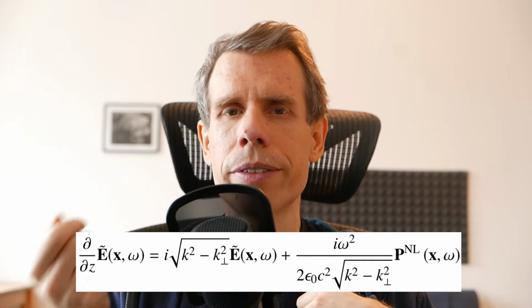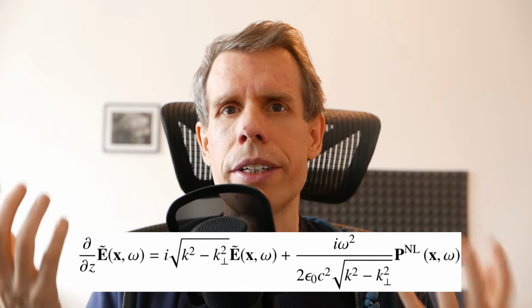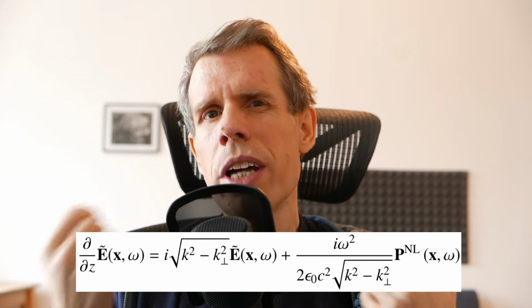So first, let's talk about what's going on under the hood. In numerical photonics, most of the time we're solving some partial differential equation. Inside of Lightwave Explorer, there are two main partial differential equations that we want to solve. One being the unidirectional pulse propagation equation, UPPE, which looks like this. And this is derived under the assumption that light is propagating primarily in one direction, which in a lot of nonlinear crystals is a valid assumption. So it works pretty well.